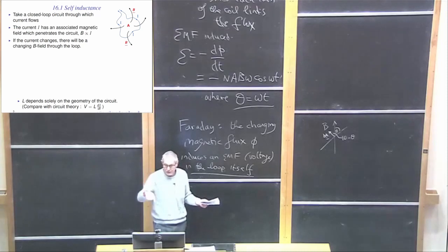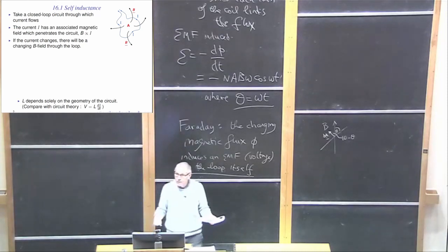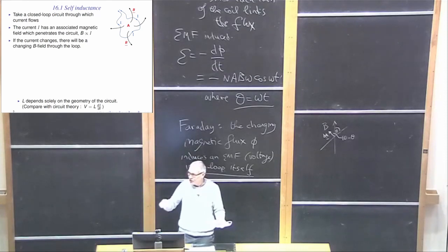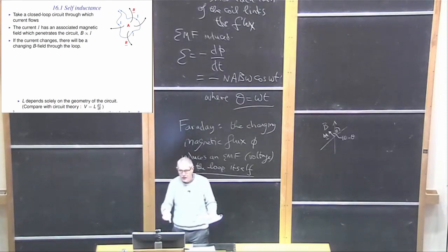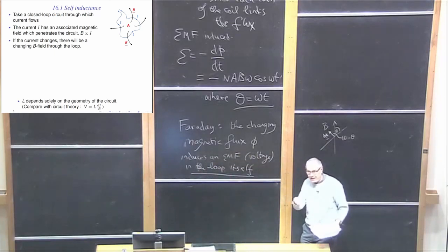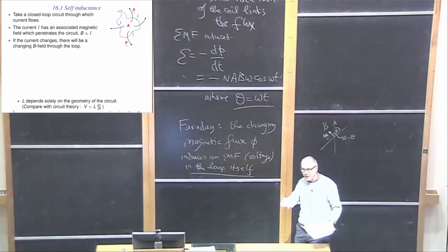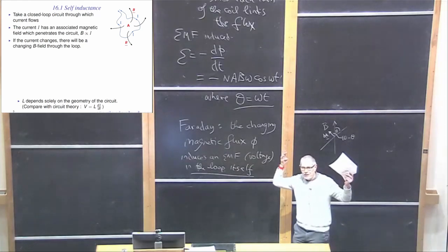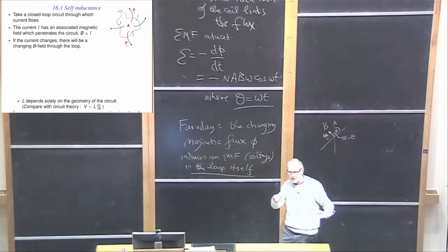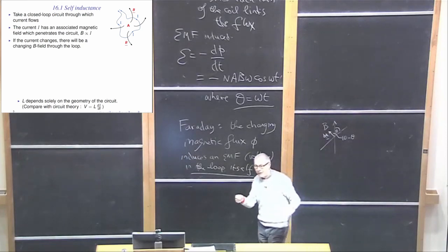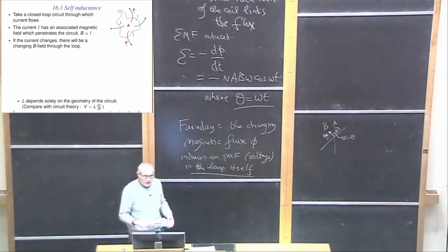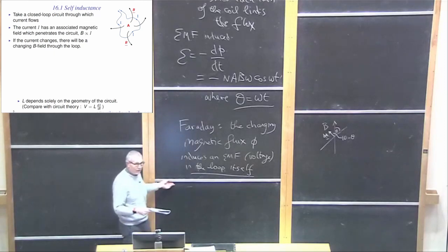If you induce this magnetic field, it feeds back into the circuit, which generates an EMF that reduces the current that caused the field in the first place. If it increased the current, the current would just take off to infinity. So it has to reduce it, because otherwise you'd have infinite energy given off eventually.